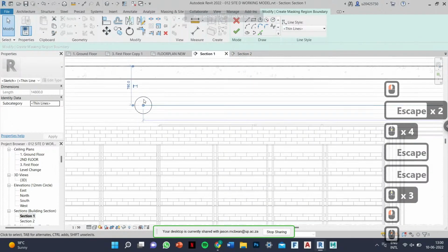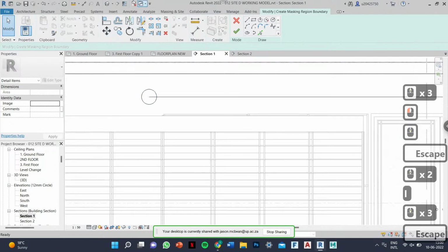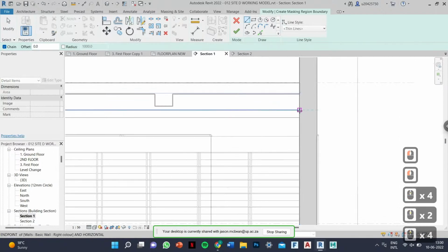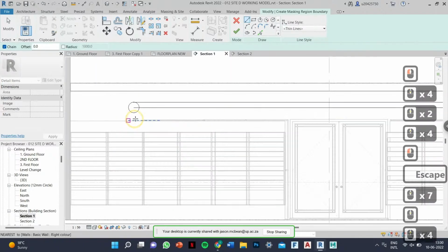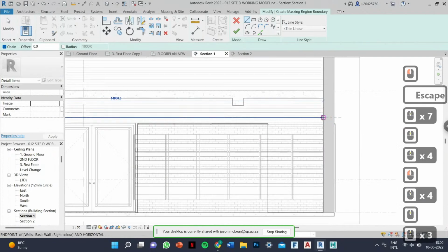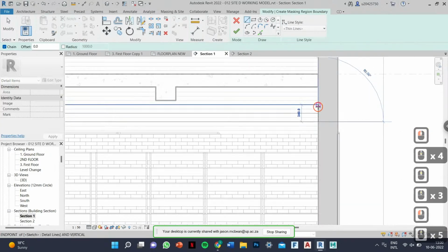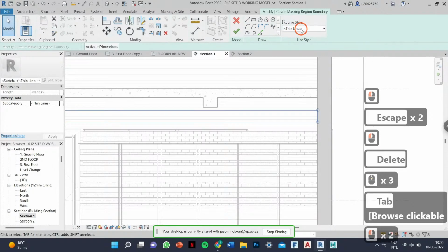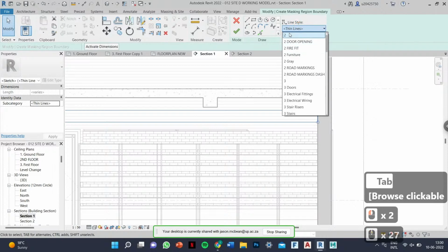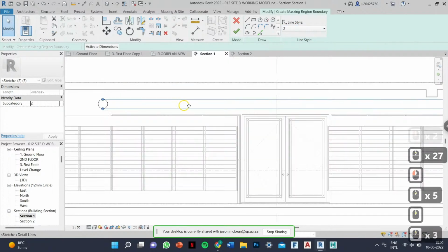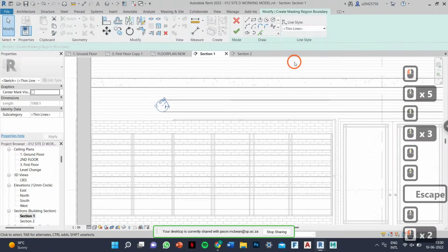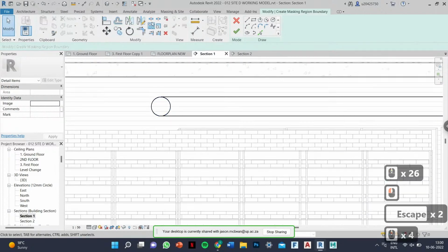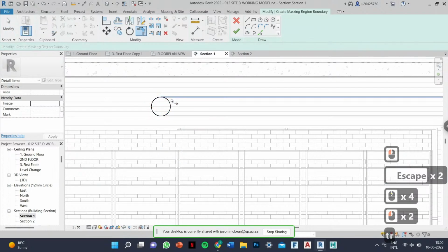Now I'm going to create a bit of line work. It'll come through the wall, and it'll now follow. These things scale up sometimes, but I'm going to do this roughly. You can add the detail, but for now, these are always closed loops. You're going to use a line size scale, either 2 or 3. Make sure that this is 2 or 3 as well, because this is linked to a line weight. Split this guy and trim.